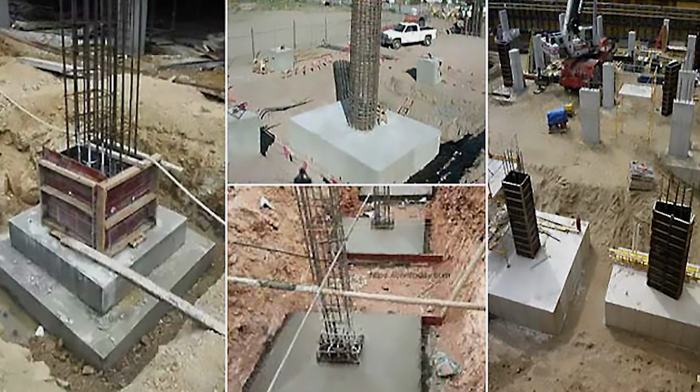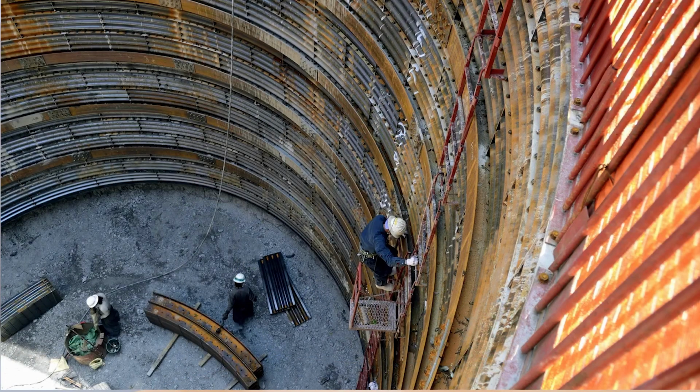starting usually with the foundation of the machinery itself. Large concrete spread footings can reduce vibration, as will large concrete caissons, particularly if you can get those caissons to extend down to bedrock. Other structural modifications can be achieved, whether that's with mass, stiffer beams, or damping techniques.